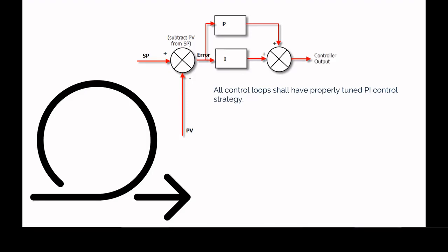So as an example, you think about a valve when you're trying to maintain a static set point, things change. The demand on the system can reduce, so more of the return water comes by. So you have what's called a set point, and then you have your process variable or the temperature, also known as the feedback, which is either over or underneath the set point, and that's effectively called the error. So that's the amount of difference between where your set point is and where the temperature needs to be. So what the loop does is a series of calculations that really try to identify what it needs to do to reduce that error.